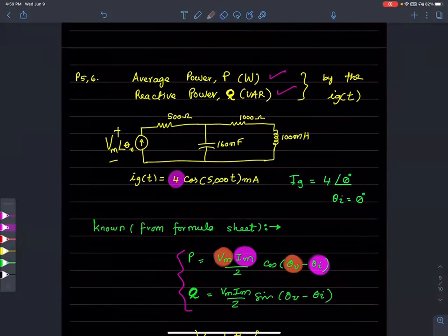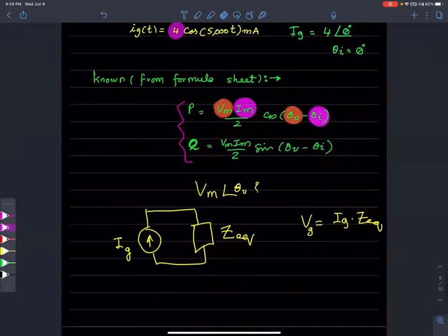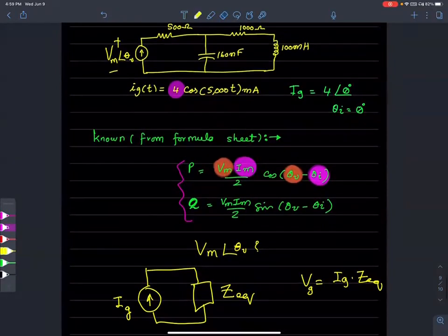So you're right. We can simplify all of this into a single impedance. First of all, we have two impedances in series that is in parallel with this guy, which is in series with this. So we can simply apply series-parallel simplification of impedances to find an equivalent ZEQ. Or in other words, you can write this as ZC or ZL, you can write this as ZC, and then you can simplify series-parallel.